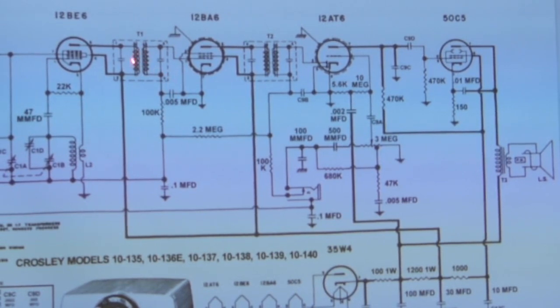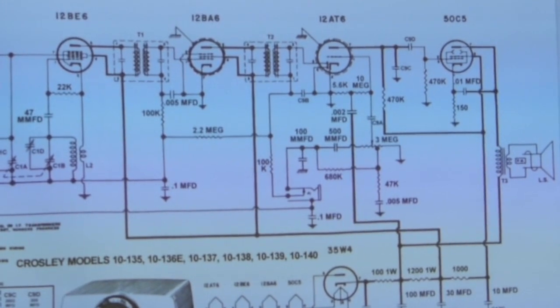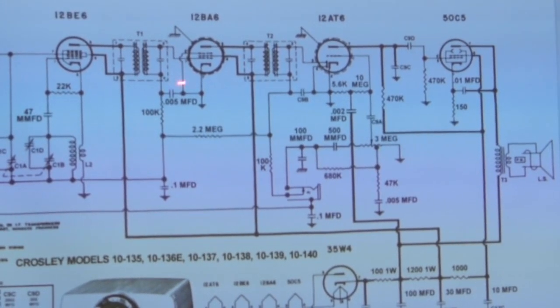Well, an open IF coil. If you have an open IF coil, what test can you do? Take a capacitor from the primary to the secondary and jump across it. Okay, but you want to find out if there's a problem in the IF. So what do you do? Ohmmeter, right. You've got your DMM. So you'll check the coil here and find out if it's open or not. You check the coil here and find out if it's open or not.